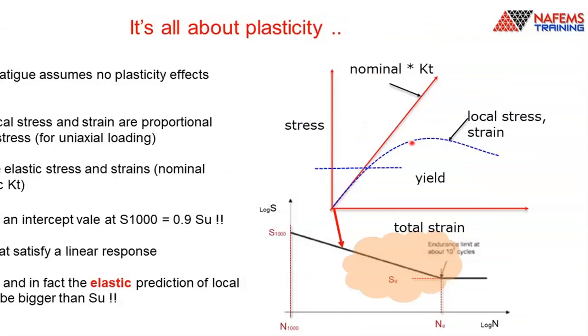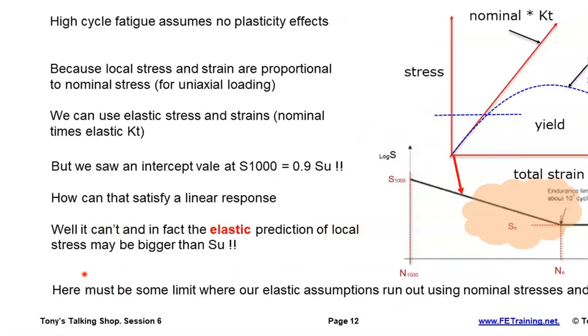And if we ran a linear static analysis and didn't do any correction for fatigue analysis, we're running linear static. And we're saying, well, hang on, we've got a crazy stress up in here. But if that's the case, then we have to take some other approach. And that approach is to say, let's use a strain-based approach, a strain life type approach.